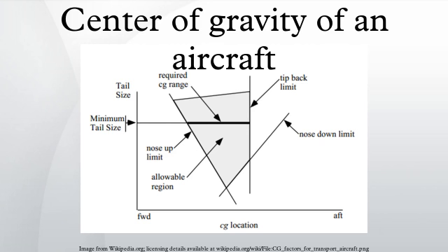In the event of engine failure and a resulting yaw rotation, the pilot may not have enough cyclic control to flare properly for the landing. A forward CG will not be as obvious when hovering into a strong wind, since less rearward cyclic displacement is required than when hovering with no wind. When determining whether a critical balance condition exists, it is essential to consider the wind velocity and its relation to the rearward displacement of the cyclic control.